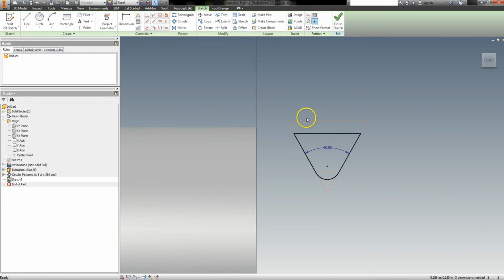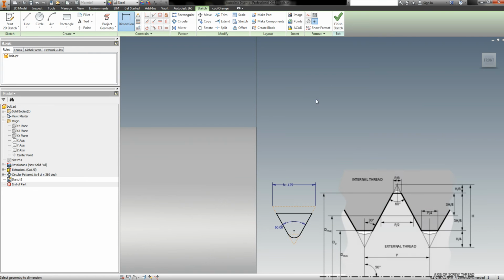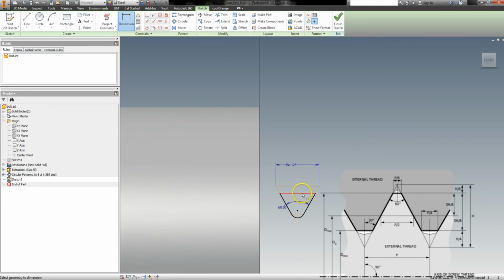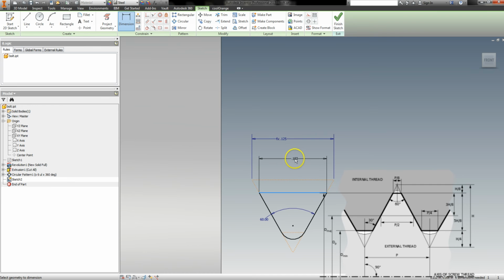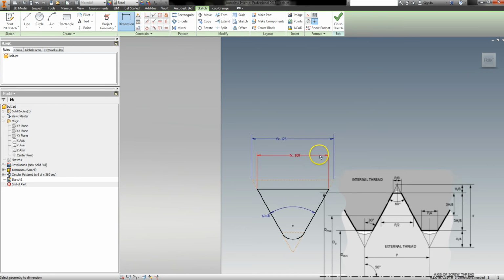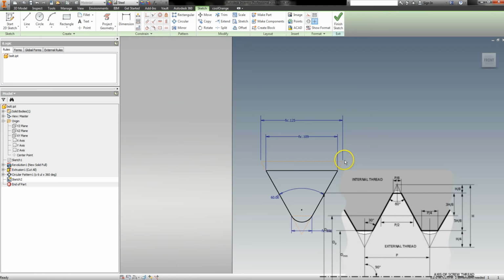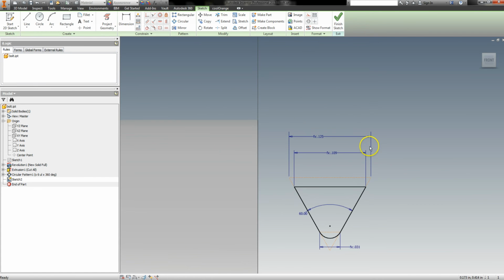So now that I'm done there for the moment, I'm going to come over here. You make the tip to tip of this triangle pitch. If you look at that, I happen to know that this leg is 0.875 times pitch. Again, this is from understanding the thread profile. And I know that this is 0.25 times pitch.